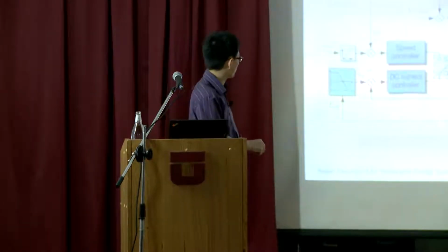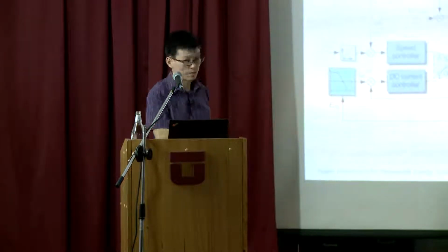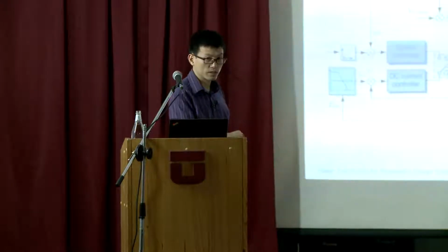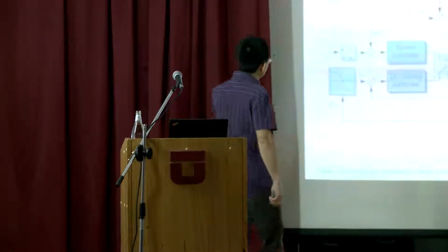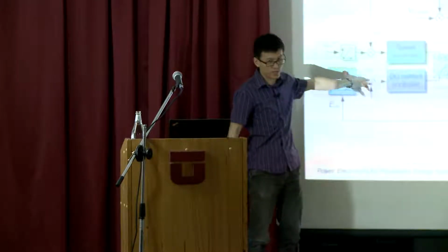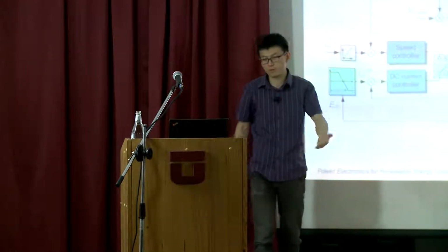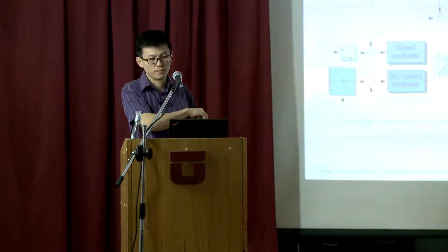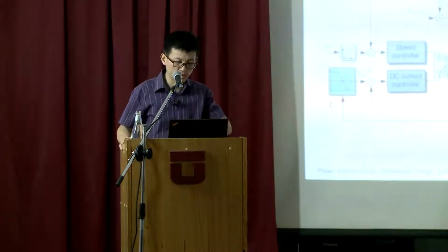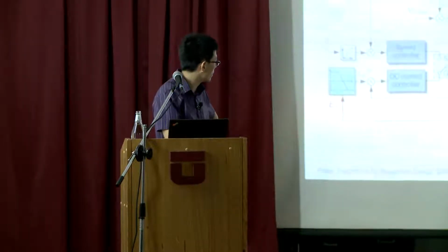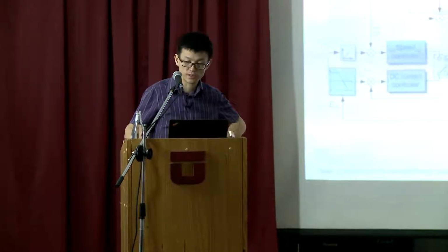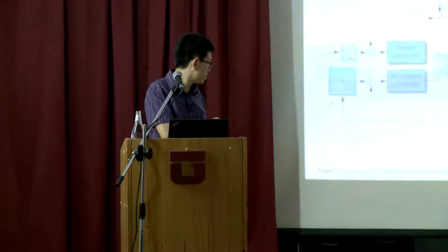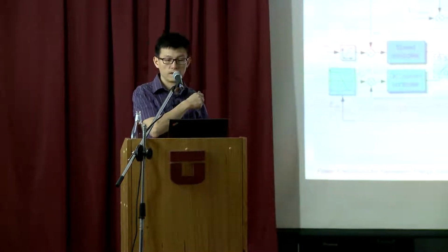And the droop itself is of course the outer loop. For this particular project, we are using current mode control, so the droop gives you the current reference. The voltage feedback goes to the droop characteristic functionality, and then gives you the IDC reference. So this is the control architecture, and we apply the droop control for the generation systems.